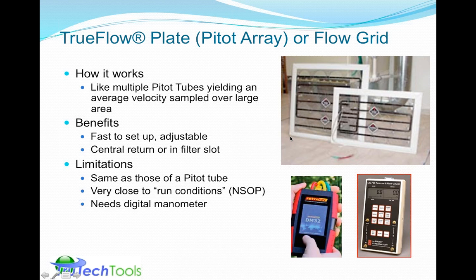The Energy Conservatory does a great job in their instruction manual. In fact, you can download it for free. I think we have it on our site, but I'll make sure that we have it up there because it gives you a very good overview of the technology and how it works and the correction factors. You do need a digital manometer to use this, and I would say you need a precision manometer and one that has the calculation for the flow grid in it.